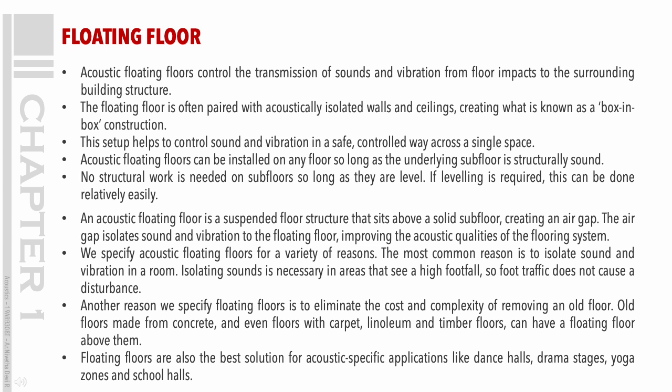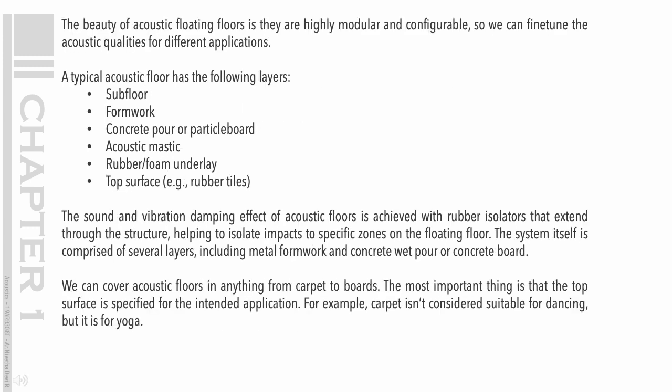We specify acoustic floating floors for a variety of reasons. The most common reason is to isolate sound and vibration in a room. The beauty of acoustic floating floors is they are highly modular and configurable, so we can fine-tune the acoustic qualities for different applications. A typical acoustic floor has the following layers. Subfloor. Formwork. Concrete pour or particle board. Acoustic mastic. Rubber/foam underlay. Top surface, for example, rubber tiles.